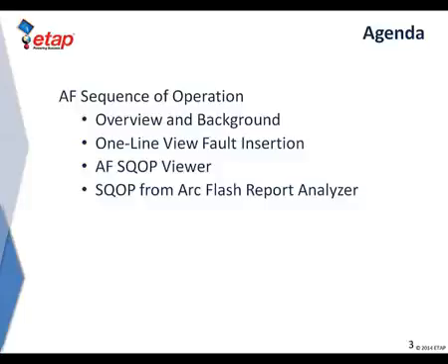So the arc flash sequence of operation has the same concept as the star sequence of operation, but with the main difference that the operation of the devices is determined based on the arcing fault current, as opposed to the bolted fault current. In many cases, coordination issues will arise because of the significant reduction in current during an arc flash event. This reduction becomes increasingly larger with low voltage systems, or voltages below 1 kV.